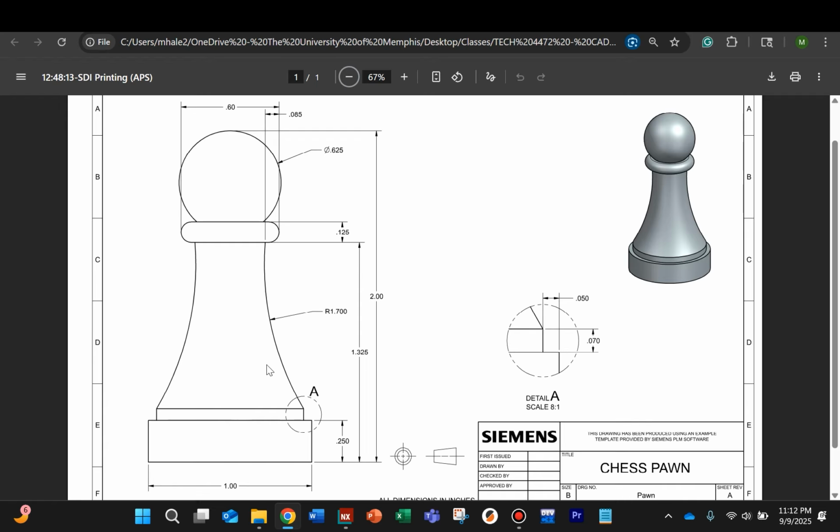So even though we have this vertical axis from the origin that technically is the center of our part, we need to define a 2D boundary. Remember, we need an actual defined 2D boundary. So we have to have a line that goes through the center here. So we'll have half of this model with a line going down the center. So everything is going to be half of what you see here.